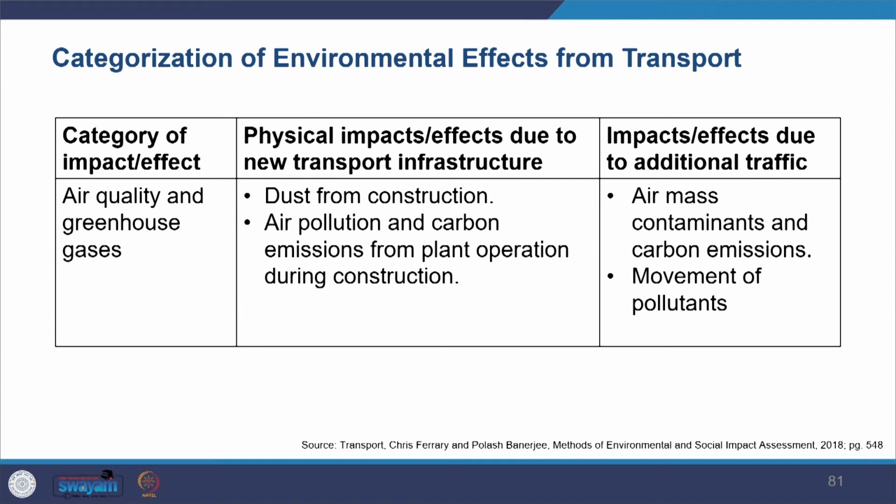Now we are going to look at the environmental impacts of transportation projects. If you look at various categories of impact, you have air quality and greenhouse gases, which we have already seen. There could be dust from the construction, air pollution and carbon emissions. In the case of transportation in particular, you look at nitrogen dioxide and particulate matter, and you might also choose what pollutant to look at depending on what kind of fuel is used most in your context.